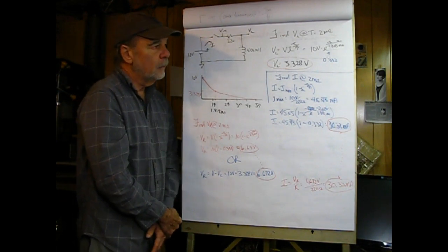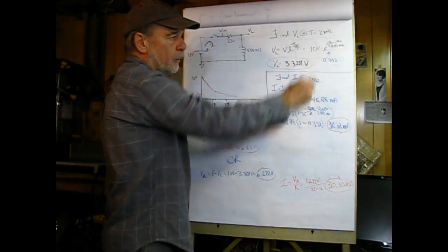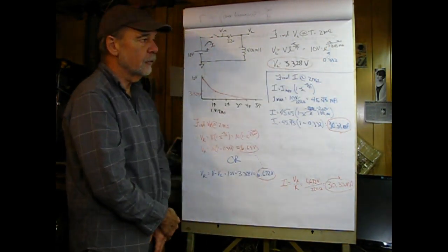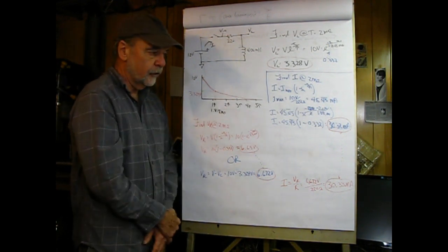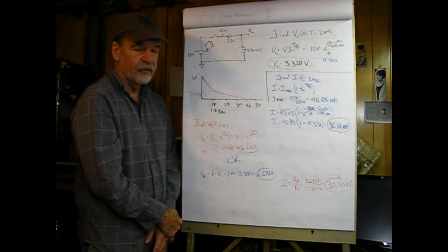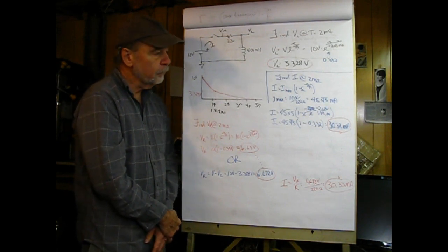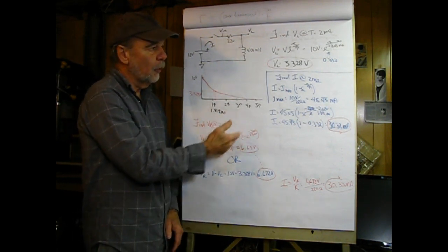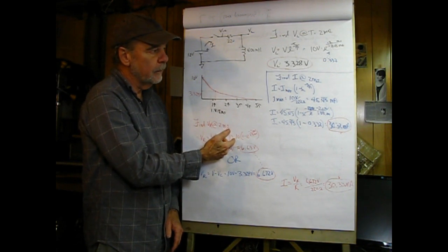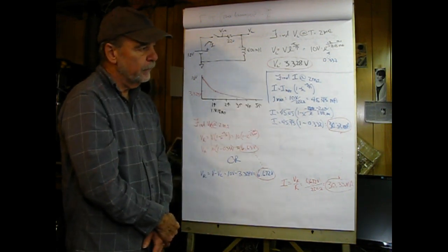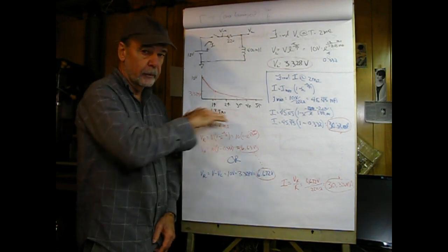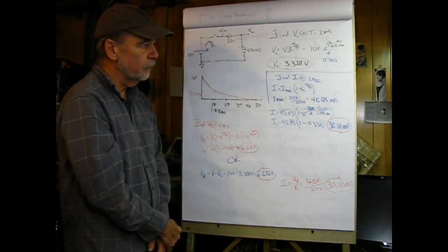The negative means that it's a decaying function, an asymptote, whereas if that were a positive exponent, the voltage would grow without limit. So when you see the negative up there, you know it's going to be a stable circuit.